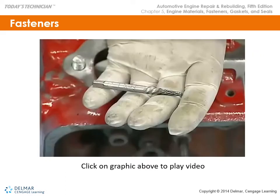fastener. This is a bolt extractor, an easy out, and I just love these names because it ain't coming out, so it's an easy out. But that's just a fun thing there. We have to be very careful that we drill the correct size hole for this easy out. So there's a corresponding drill bit number to utilize for that, and it tightens to the left.